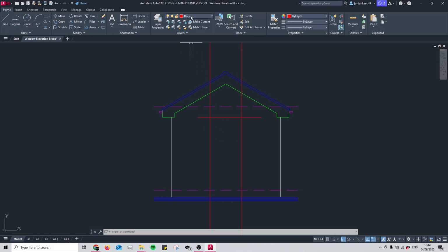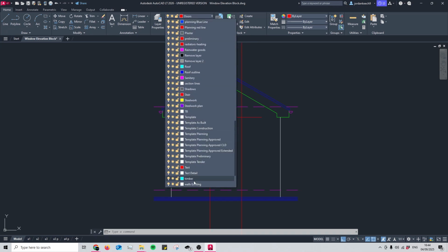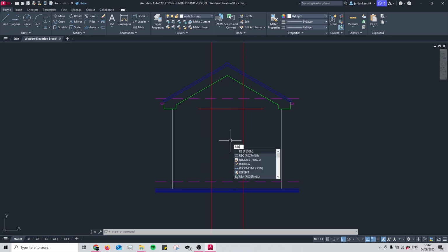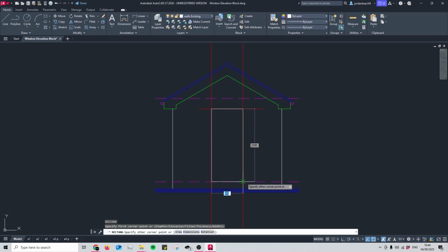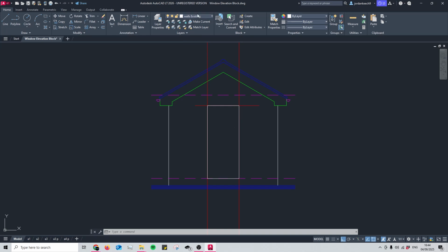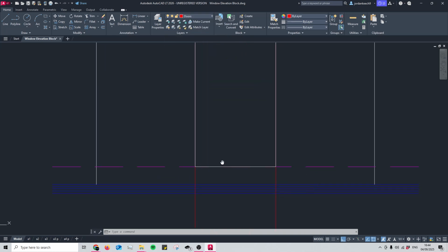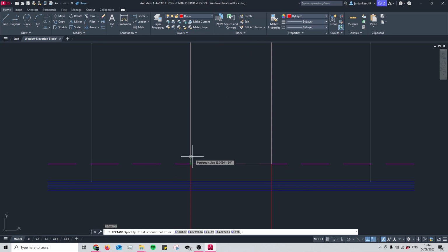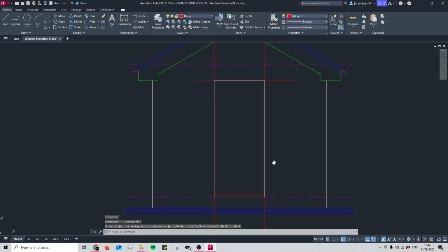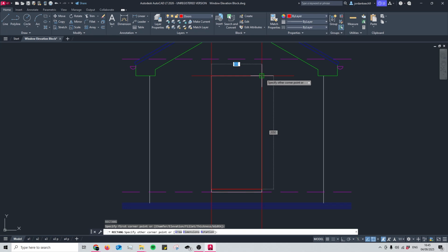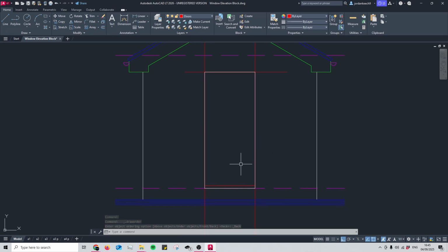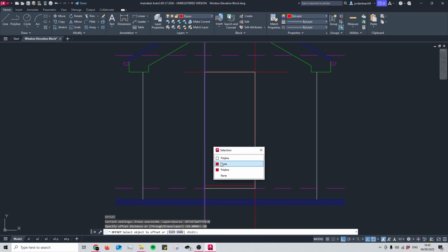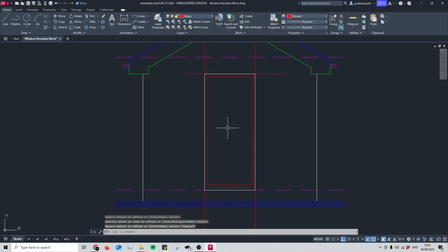To begin with, I'll select the layer that I've used for my walls so far, and this will be to indicate the opening into the building. And I'll simply do this by drawing in a rectangle. Then, using the door layer, I'll draw a 50mm tall rectangle across the bottom of the doorway to create the sill. Then I'll use another rectangle around the rest of the door above my sill. Once both of these rectangles are in place, I will offset the upper rectangle inwards by 50mm. After that, using the same process again, I'm going to offset by 100mm to create the frame around our glass.